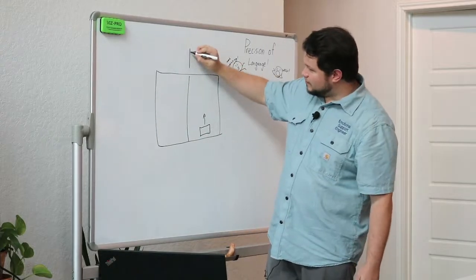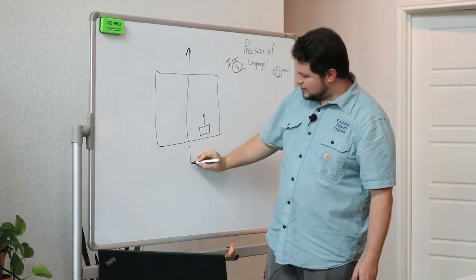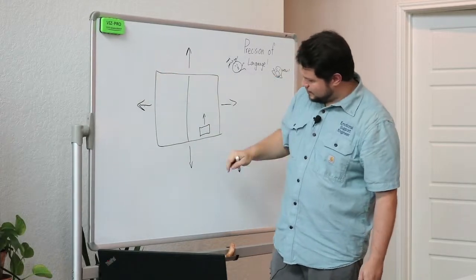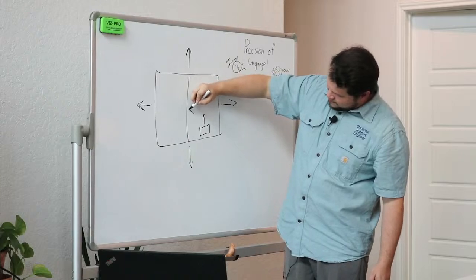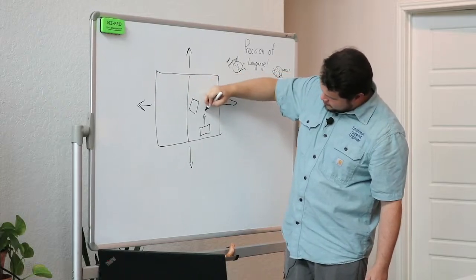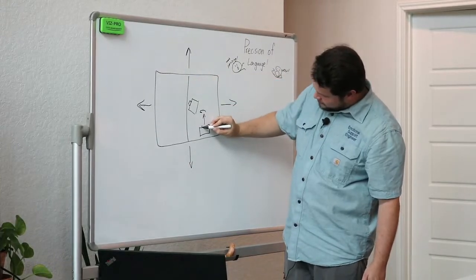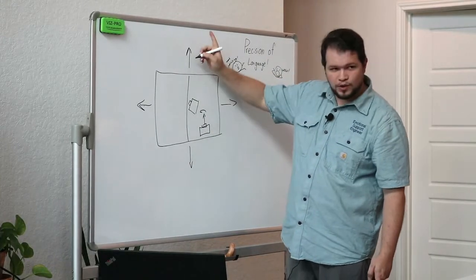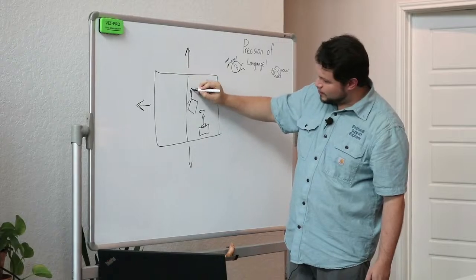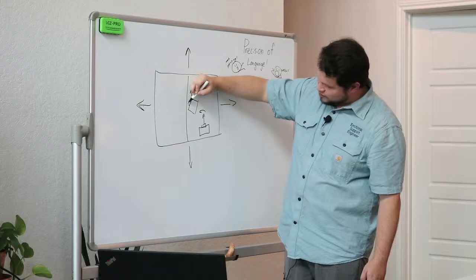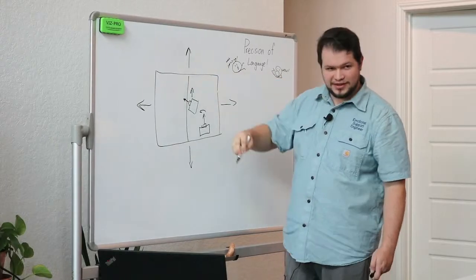It looks at the field and says this is forward, that is back, that is right, that is left. So if my robot is here, because I've spun to get there, and the front of the robot is on this side, and I press forward on the joystick, it is going to move that way. That's field-centric, as opposed to robot-centric, where if I press forward on the joypad, it would move that way.